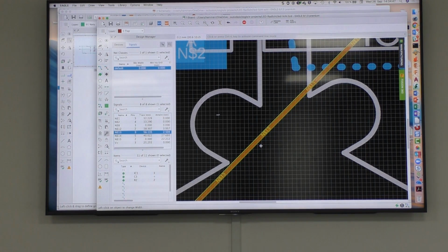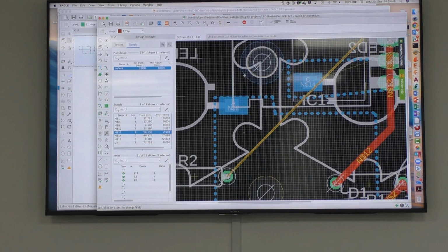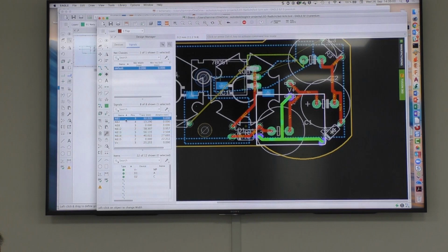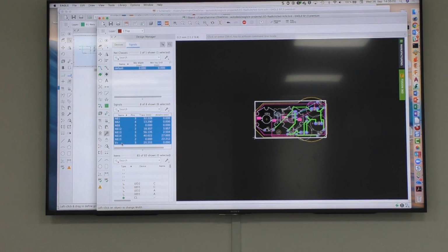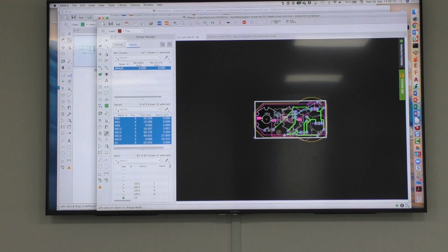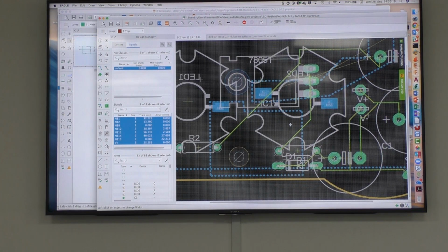So for example, if a student came to me and they'd routed their PCB all with 0.1 millimeter wide tracks, which happens, can I select all traces with the design manager? Yeah, you think you do this one? Okay, select in an editor. Let's try. Okay, and change width. 0.1 or something like this, it doesn't matter. And then control right click. No, it says click left. Yes. Yeah, it does it. You see? That's great.